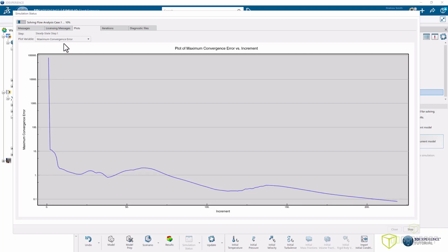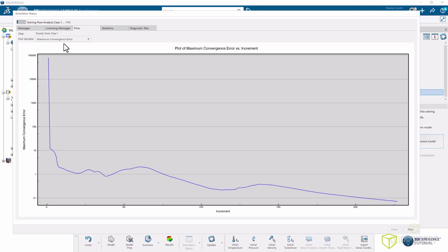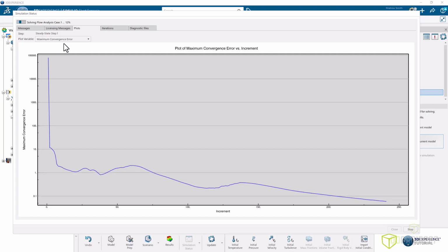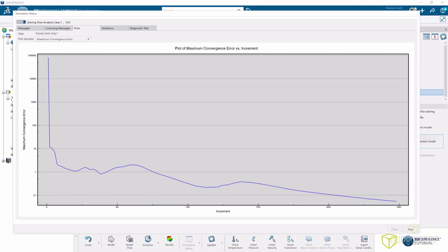The error allows us to basically look at the trajectory of the residuals and, without getting into the real technical details, say, oh, even though it says it's resolved, or the residuals say it's converged, we still need to work on this more because the initial guess was bad. Or, hey, even though we can't get residuals to go 4 orders of magnitude smaller, we actually are getting where we should be, it's sufficient, the error's not changing. So it can be a little bit more conservative and reliable way of ensuring that you have convergence. And there'll be more on that later as well.